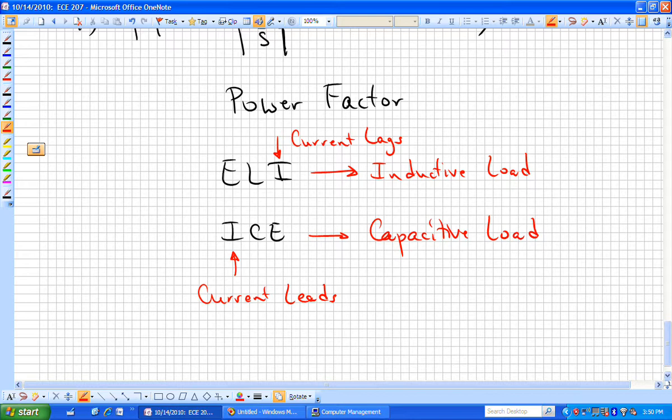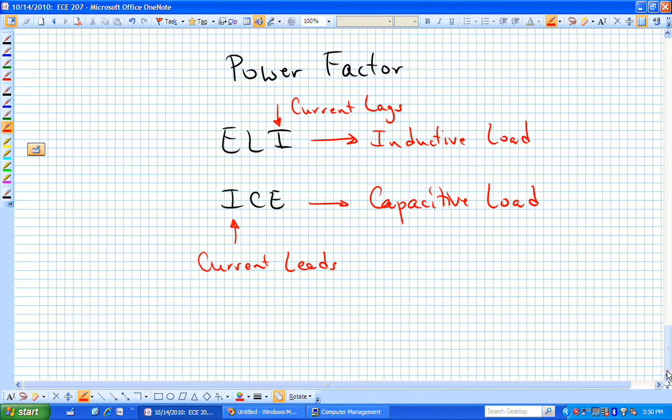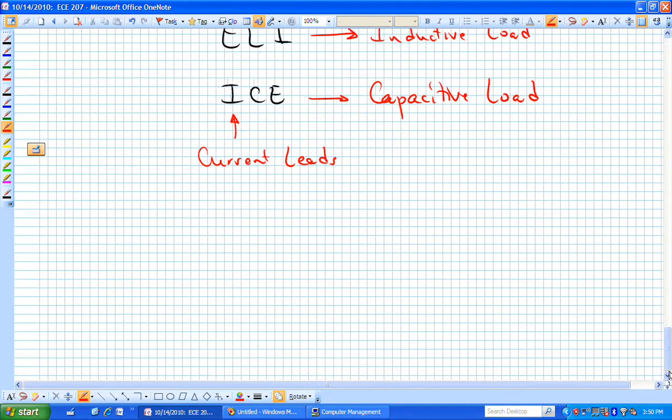Those are our observations relative to complex power. We have a real part, average power, an imaginary part, VARs, an apparent power, which is really the length of our hypotenuse, or the magnitude of our complex power, and we have the angle. And one way that we can keep track of all of that is simply to draw this triangle, and that triangle is called the power triangle.